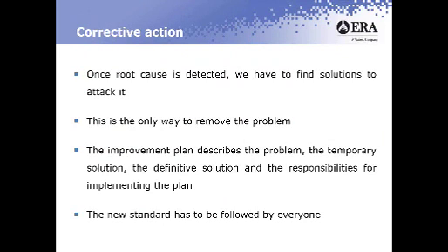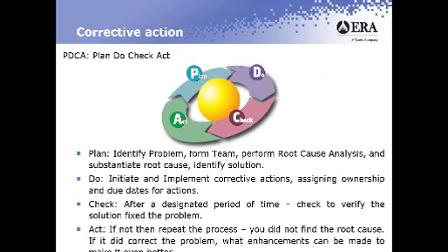So if we follow the PDCA methodology, which is really we need to plan, do, check, and act. If we look at plan, what's plan mean? It means we're identifying the problem. We're going to form our team. We're going to perform root cause analysis. We're going to gather data to support and substantiate what we think is our root cause. A lot of times, the planning piece is probably the most difficult, again, getting the root cause, because many times we don't go and substantiate the root cause. So having facts and data and not just tribal knowledge is very important.